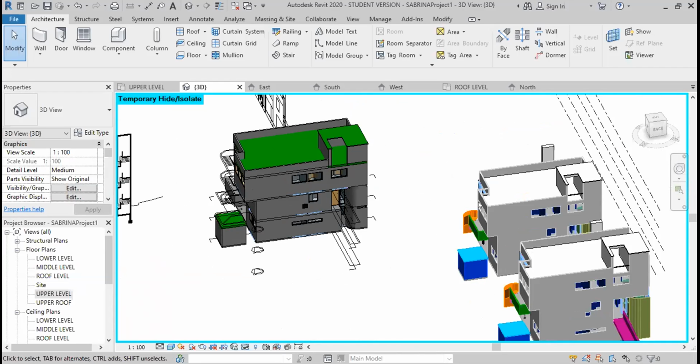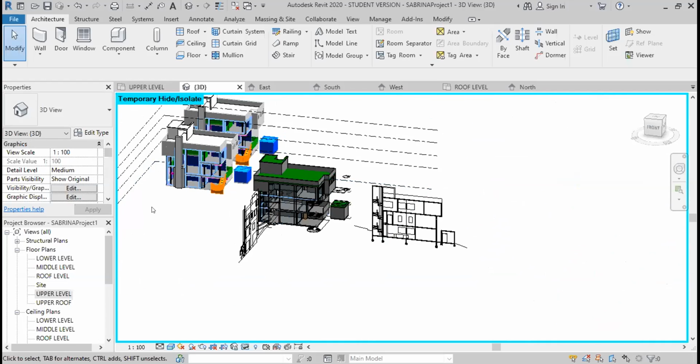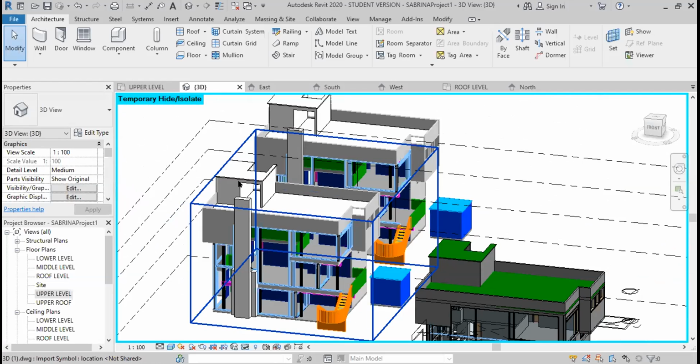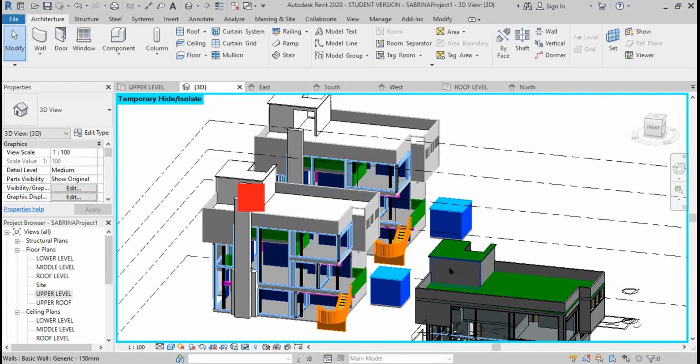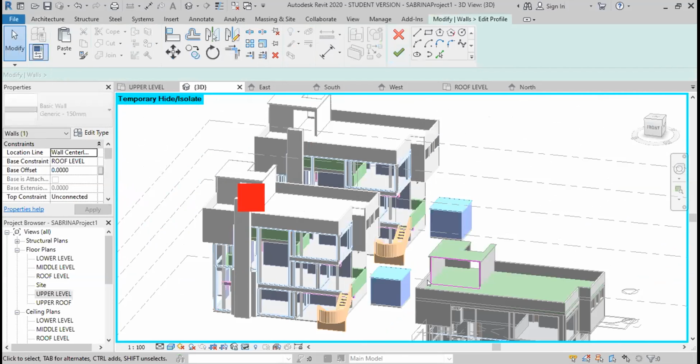I have another question. I don't understand. Sorry, what did you say? I have another question. So like, for the roof, the shed on the roof, I do not know how to make that thing. The opening for what looks like a door. I don't know how to do that. This one? Yeah. Simply, you just edit profile. When you edit profile, actually now anything, if you draw a square here, that square will be an opening. So basically, you need to know the dimension, if possible, of that opening, and you draw a square equal in size of that opening. Okay.